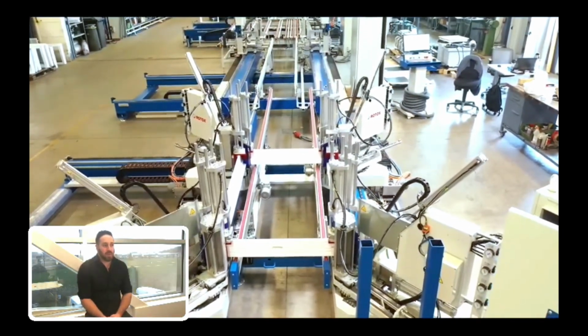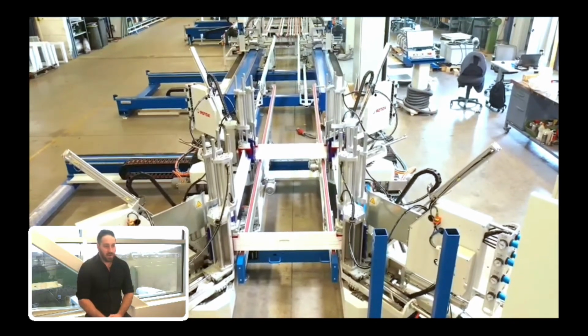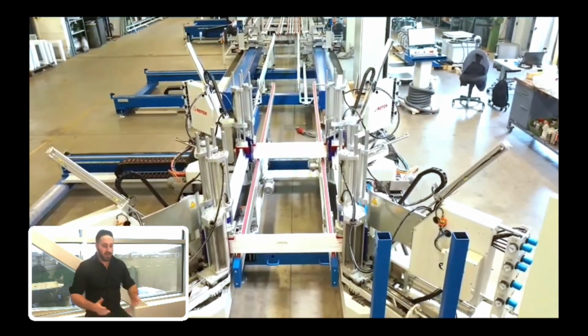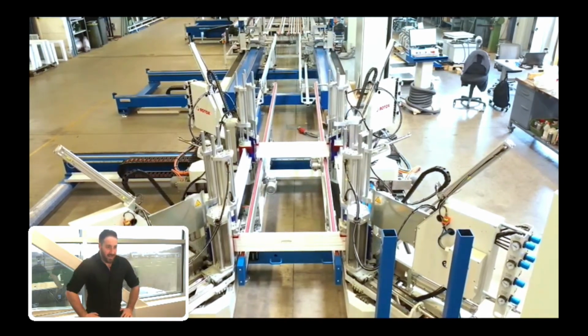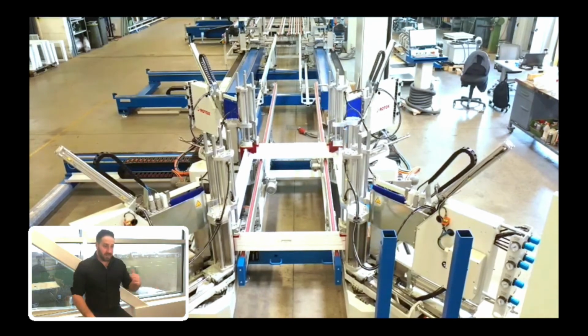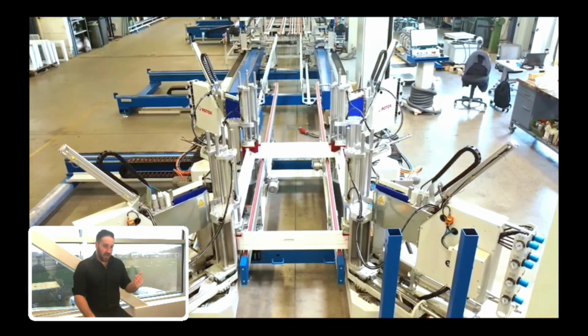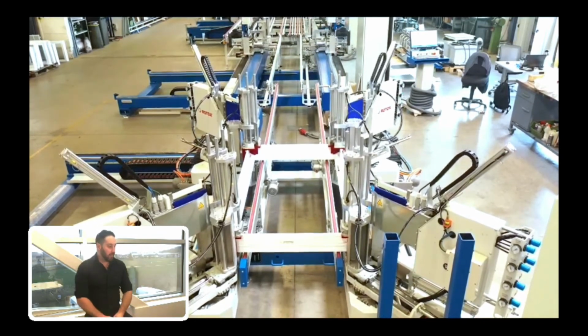So again, if I'm using that 1000 millimeters example, well, your glass stop is going to have to be, let's say, 990, but if the window at the end is really 999, well, the welder is going to send the information to that saw, making sure that the glass stop is shorter as well, so it fits right in.